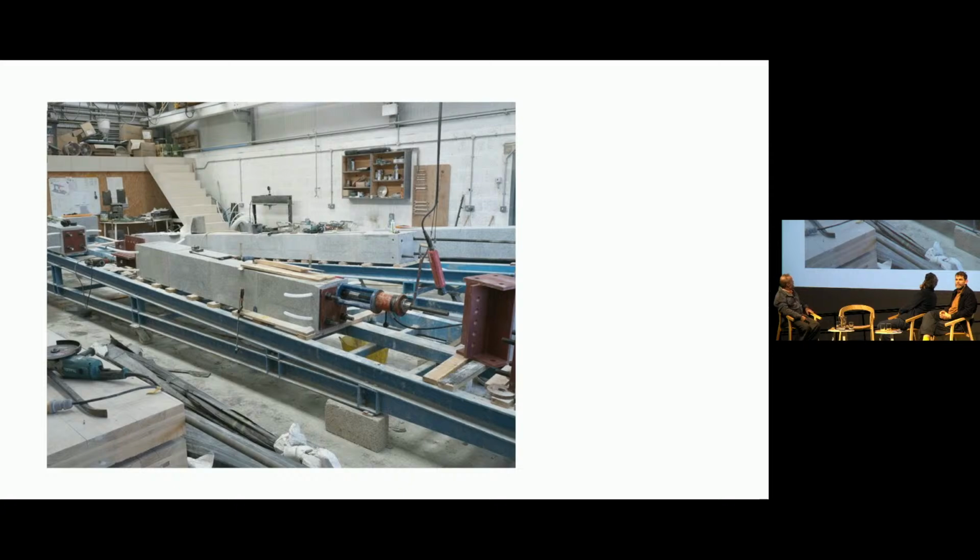And here is the assembly line that we now have in place at the workshop. You can see here we've got rigs on which we fit our stone. We've got all the bolts, Dywidag bars, the rebars that go through the columns. Usually it can be 2 or 4, depending on the loading. And we do all that prefabrication off-site. That's very important. We do everything as a prefabricated structure off-site.